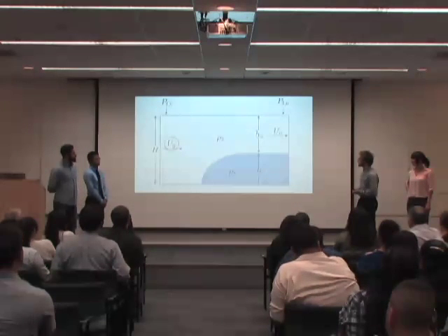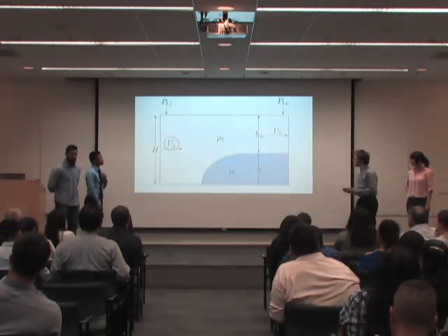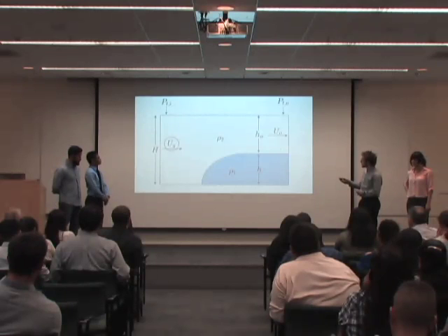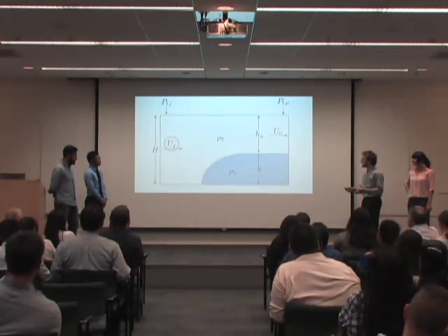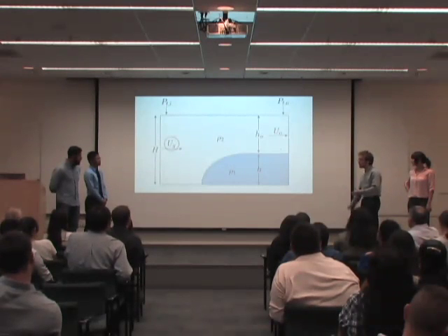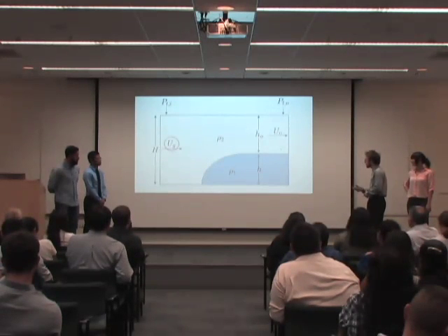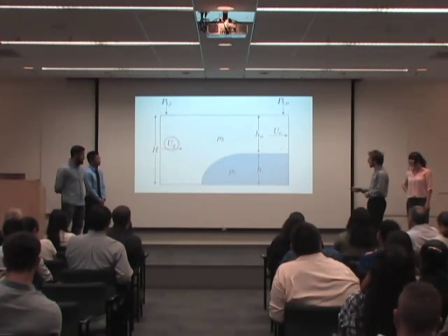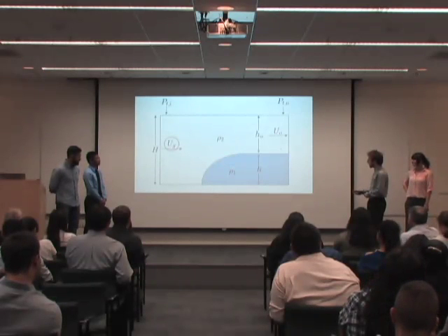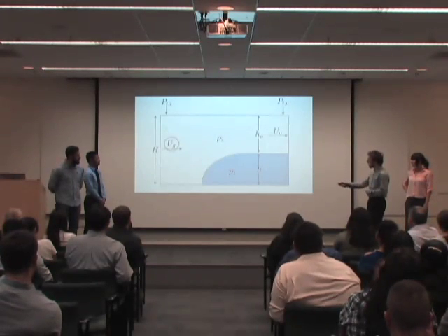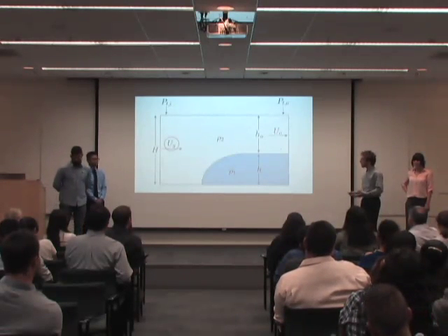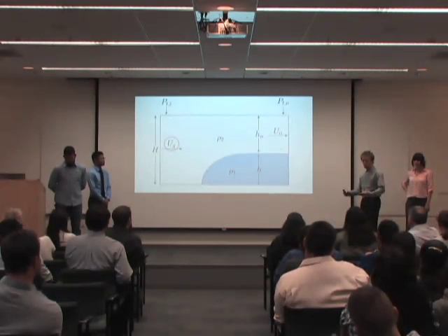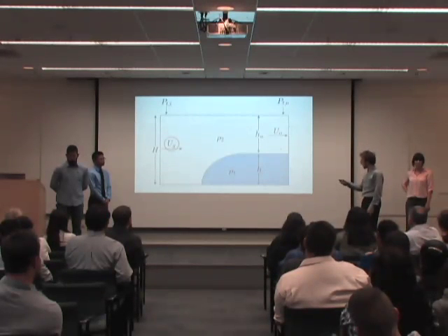In order to make this problem easier to solve, we employed a strategy: we changed reference frames. Instead of being a bystander watching our sandstorm go by, we're pretending that we're riding on top of this gravity current, watching the ambient flow past us. This is similar to how when you're driving in your car, you feel like you're sitting still while all the scenery is rushing past you.